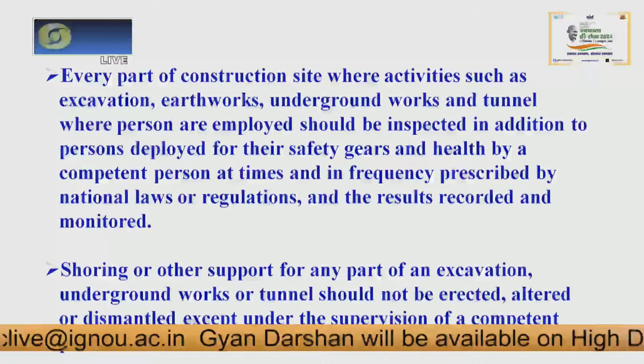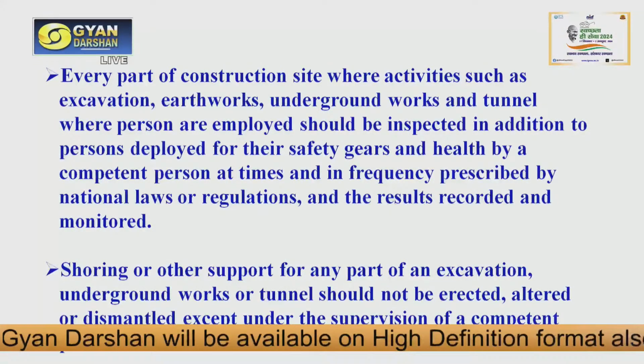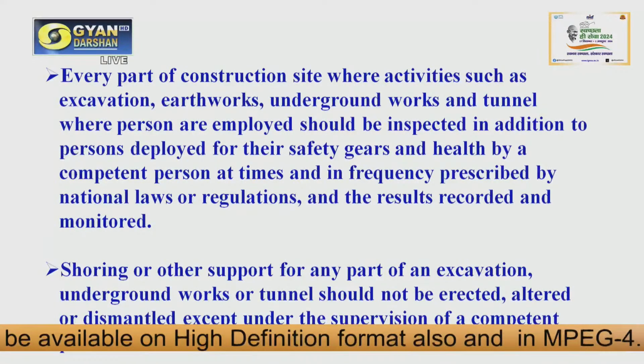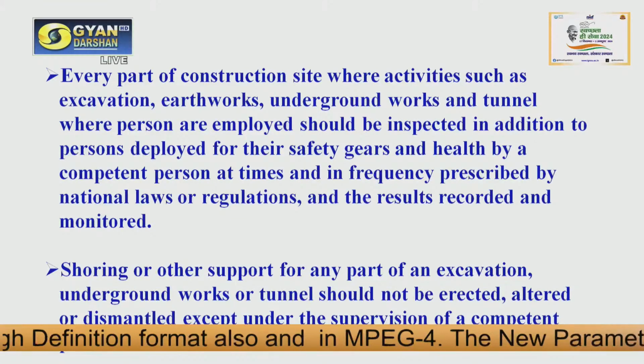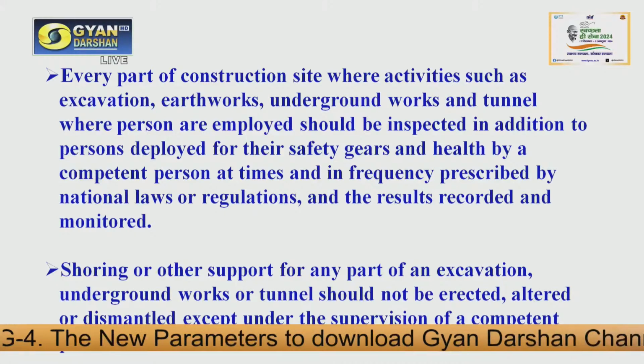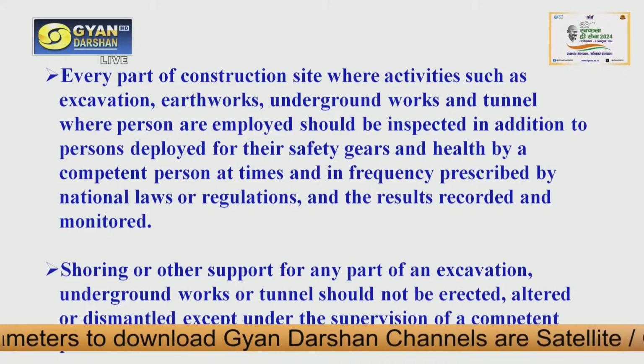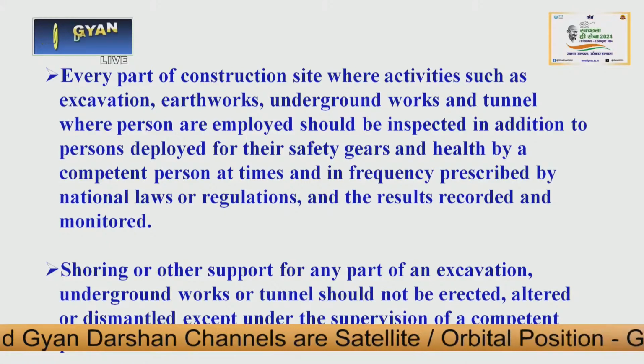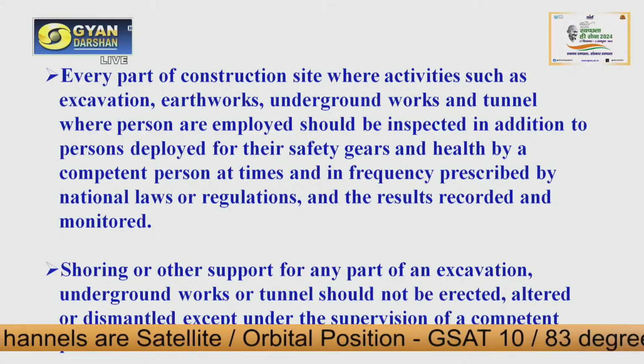Then every part of a construction site where activities such as excavation, earthwork, underground work and tunneling are carried out and persons are employed should be inspected, in addition to the persons deployed, for their safety gear and health by a competent person at times and frequency prescribed by the national laws and regulations. So here it says it is not only inspection before starting the work. There should be regular inspection from time to time while the work is going on, and the frequency should be as per the guidelines of the national laws and regulations.